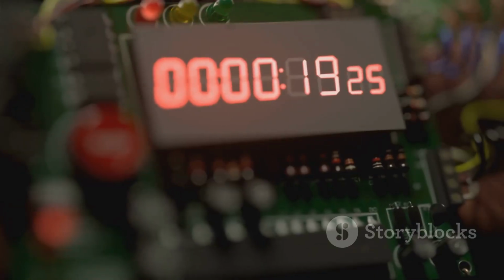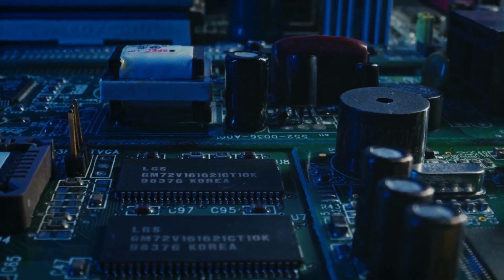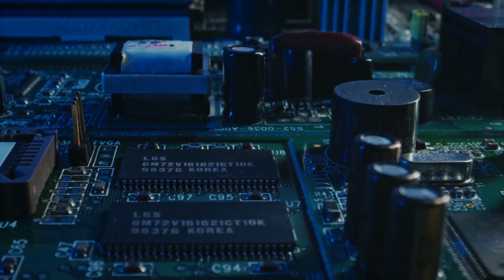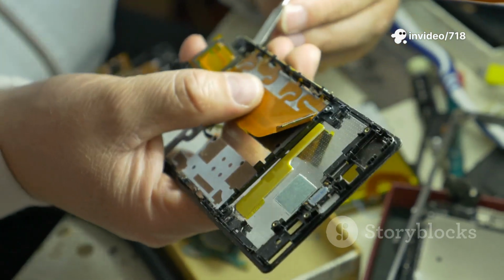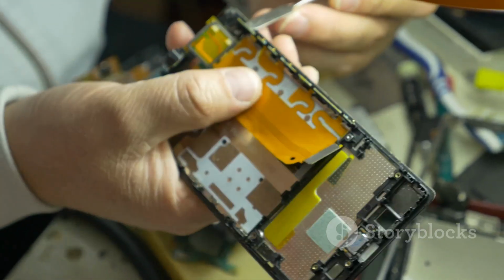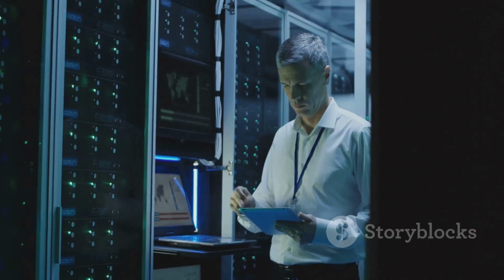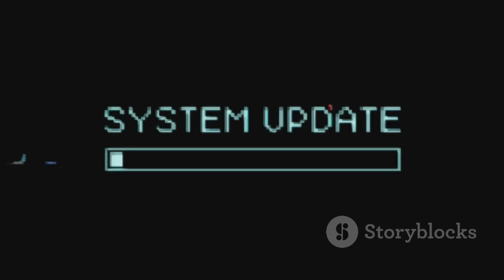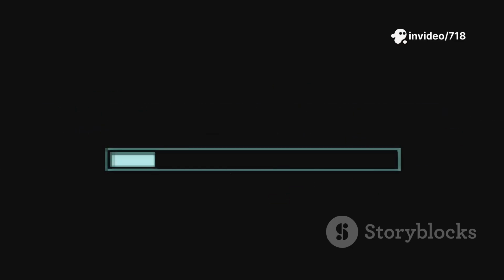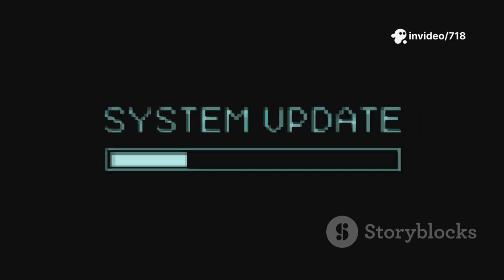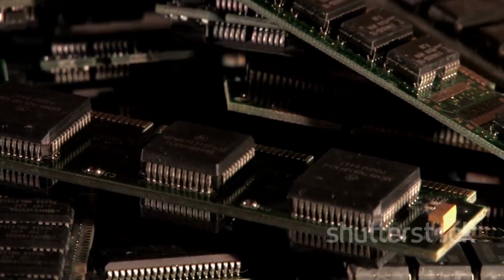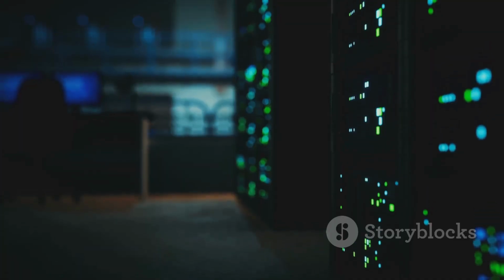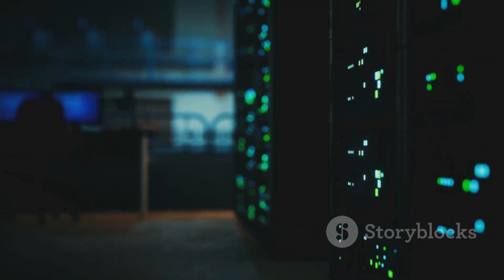It doesn't sound like much, but for a computer that performs billions of operations per second, 64 milliseconds is an eternity. The memory controller accomplishes this by issuing a special refresh command, which basically performs a dummy read and restore cycle on a row just to top up the charges. This happens continuously in the background. For a brief moment, the DRAM is unavailable for normal read and write operations, while it's busy refreshing itself. This refresh overhead is the small price we pay for the incredible density and low cost of DRAM. It's the dynamic tax that keeps our digital world running.